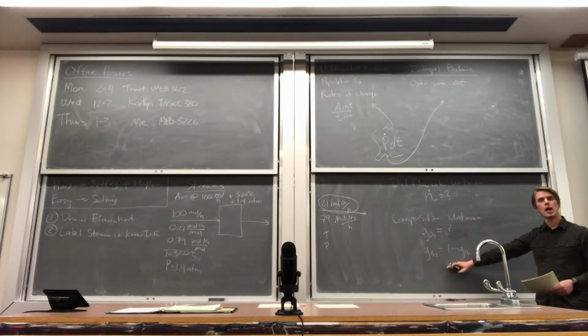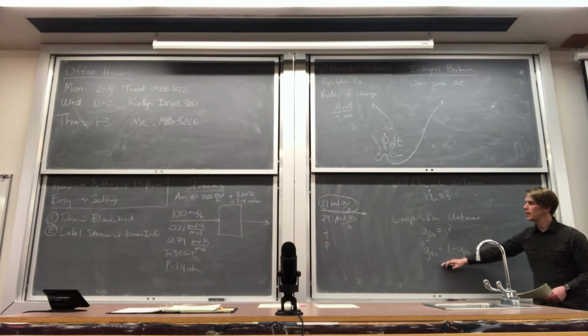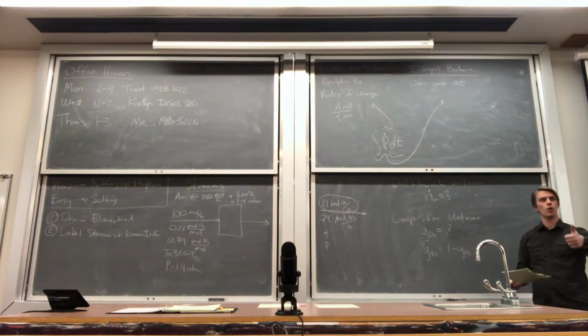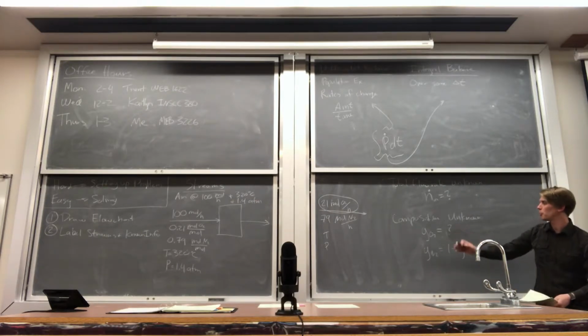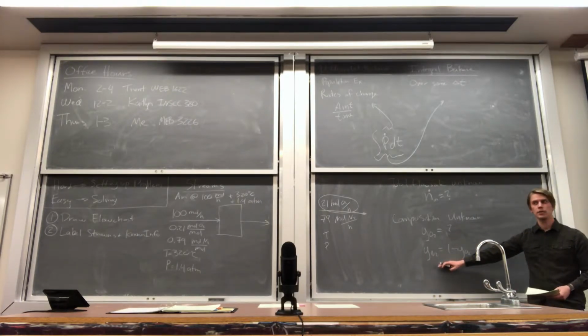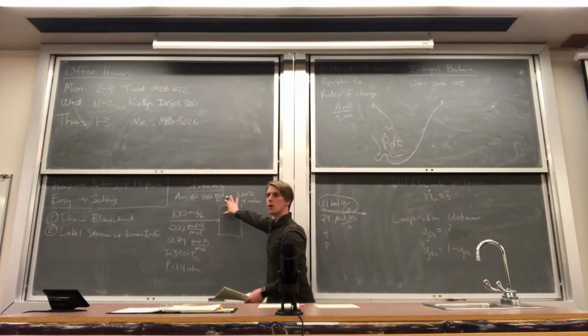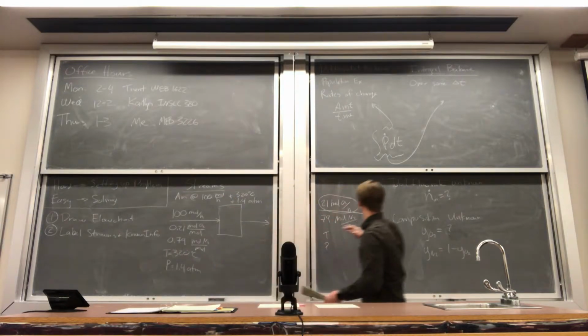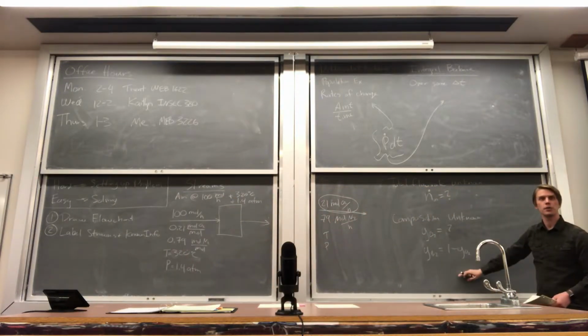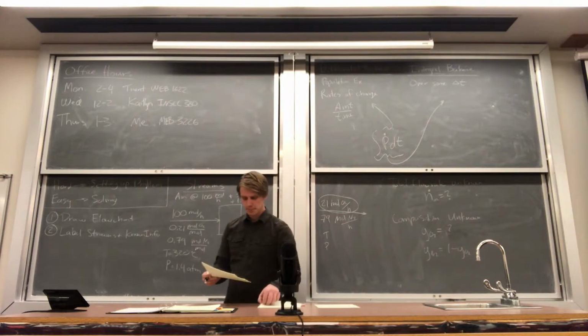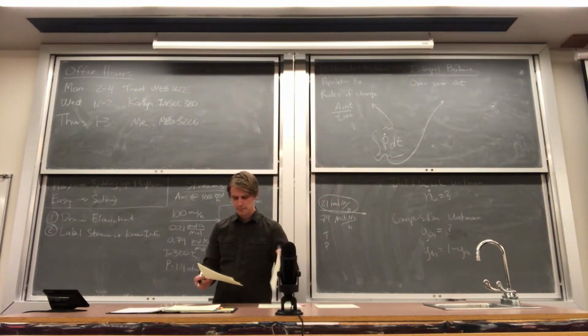So depending on the problem, you may not know the inlets or you may not know the outlets. But the key thing is, for every single property of a flow stream, whether it's the flow rate, the composition, the flow rate of an individual component, the temperature or the pressure, we need to have a nomenclature system ready and prepared in order to translate a word description of the process to actual mathematical terms that we can substitute and solve for. Okay.